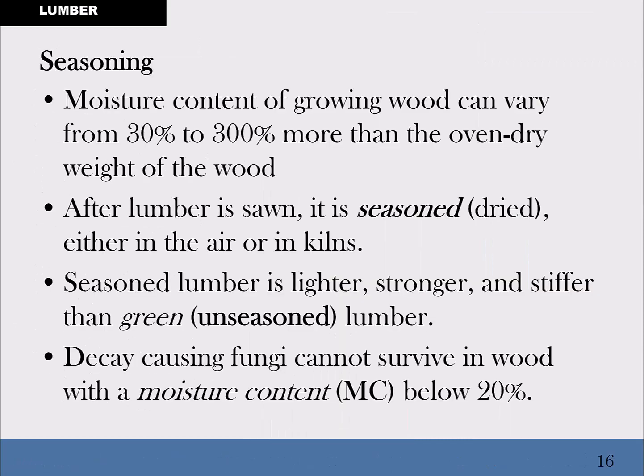So, seasoning. It's not Cajun seasoning. We're not trying to eat this thing, but they talk about seasoning of the lumber. So that's the idea that the moisture content of growing wood can vary from 30% of the weight to 300% more than the oven dry weight of the wood.